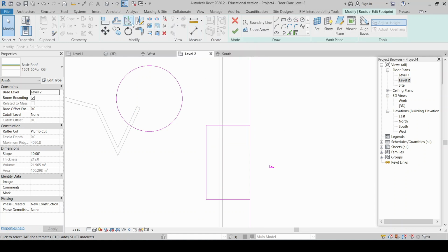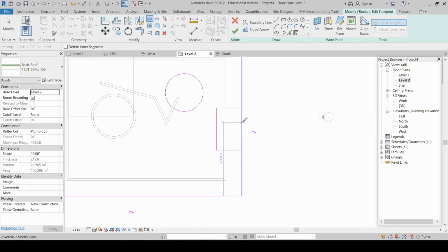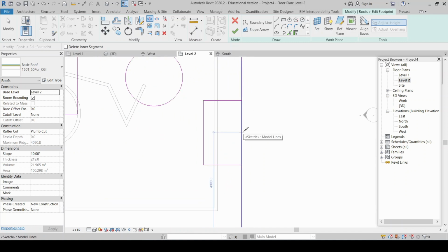So if I click on the split element, which is SL as its shortcut, I get a little knife that appears on my cursor, and I can hover over any element, and there's a little cut line that appears as I move around, and it will tell me where I'm going to cut the element. So I just need to cut this line because at the moment it's a continuous line. I need to break it into two parts and create a gap in the middle there. So I click on that.